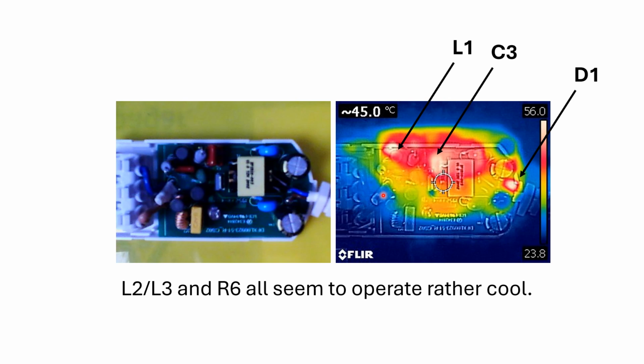They are in this bottom part here, and we can see that most of the heat is dissipated in L1, C3 and D1, and the components I placed or replaced all seem to operate rather cool. So this looks promising.